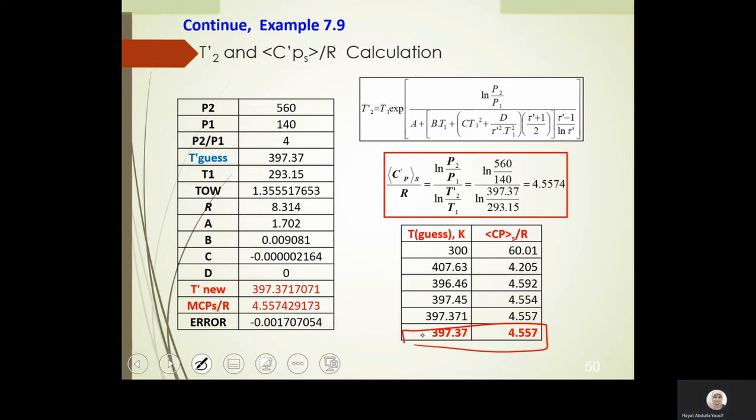Okay. In terms of the equation, since it has the same concept as the compressor, then W is equal to delta H again. But that W here is only equal to delta H if I have what? If I have an adiabatic process, Q is 0. So that's why I have WS equal to delta H. And the problem here is how to get W isentropic.